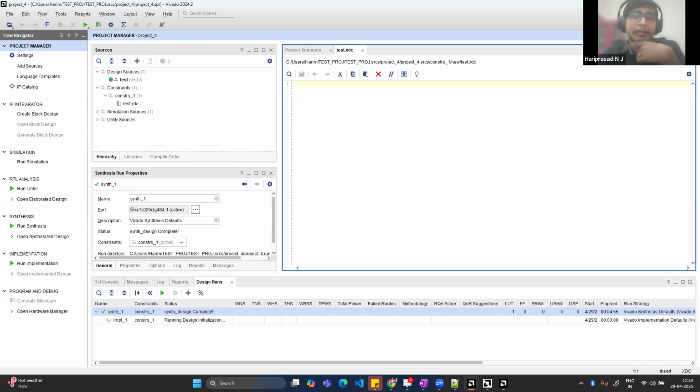No. Actually, these are analog parts, right? Those things you cannot implement on the FPGA side. FPGA is for whenever you have some digital applications, like a communication system, or crypto, or if you want to experiment with anything related to quantum. Those circuits you can implement. Those analog things you cannot. This whole FPGA is built on top of FinFET itself. It is a FinFET technology. But those things we cannot implement on the FPGA.